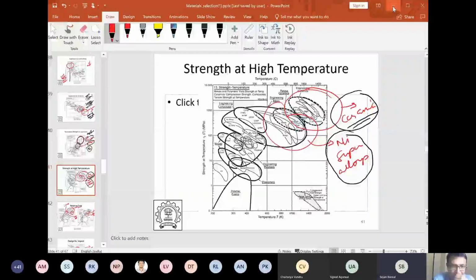Okay. So let's say I have a polymer which is reasonably light and reasonably strong. Will the polymer still be a suitable thing? Let's say we have the required strength. I'll just tell you, the biggest problem with polymers is they exhibit creep. If you have a constant tension with the polymer, it will start to become loose. So even though it has sigma y, it's not a suitable thing to use.